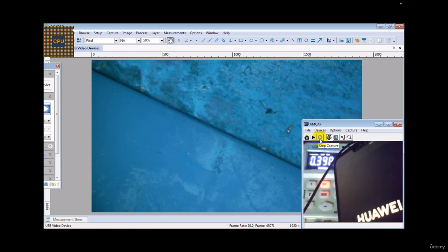In this case, we will accuse a CPU or NAND. So we will connect the phone to the computer itself. If the computer reads the phone, this means that the CPU is working properly. In this case, we will accuse the NAND, so we'll do the software to the NAND.